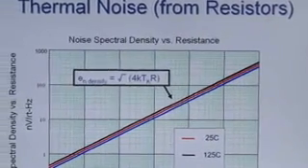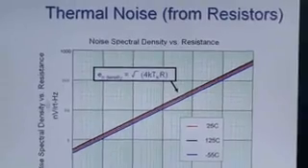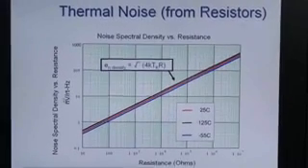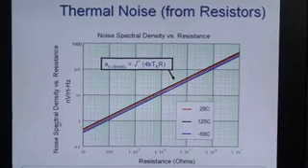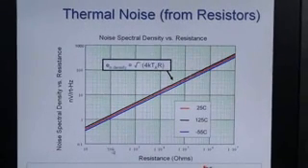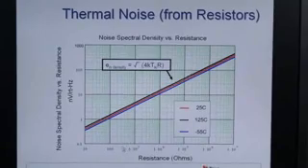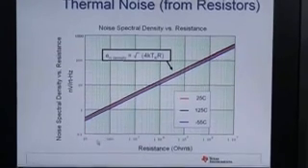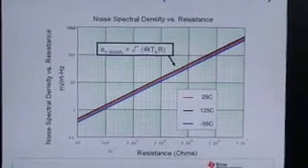The thermal noise is noise from the resistors. This plot is a very handy plot to keep available when looking at or analyzing your circuit. Without a detailed analysis, you want to just compare the resistor noise to your op-amp noise.